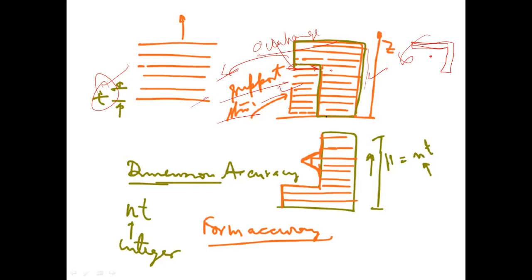Okay, so you have a minimum area of contact as compared to this, which is the maximum area that could be in contact. You have taken the minimum area of contact. Now, before you start fabricating, you decide whether this needs support or not. So orientation is added with support decisions also.